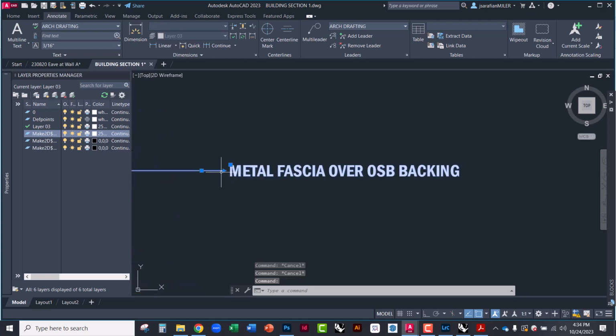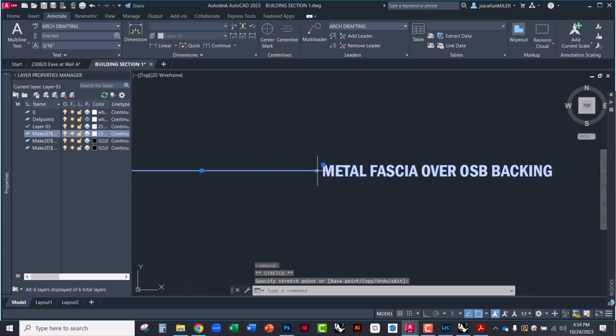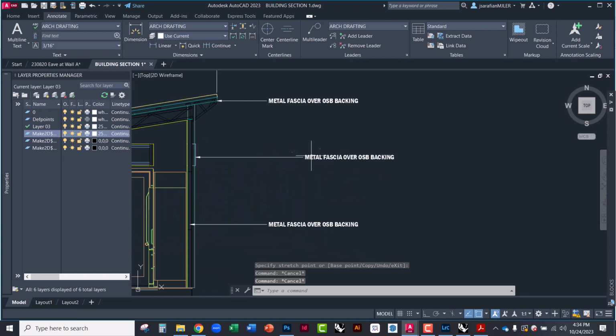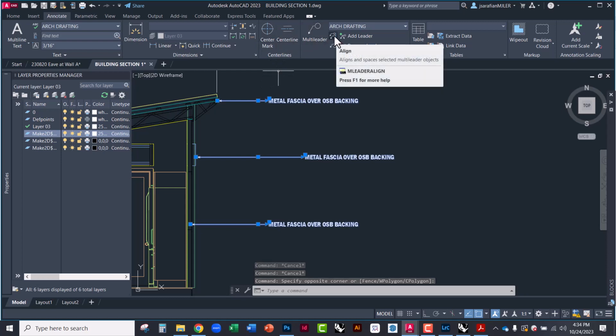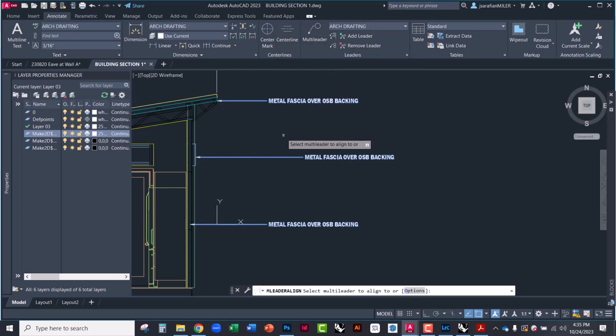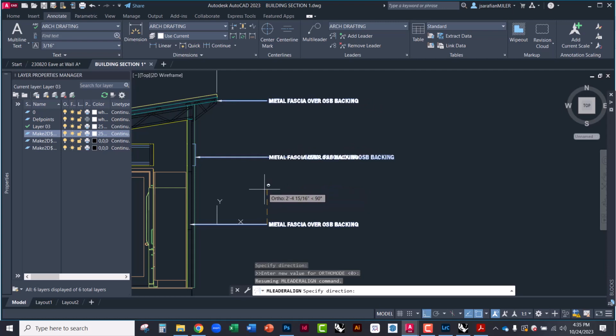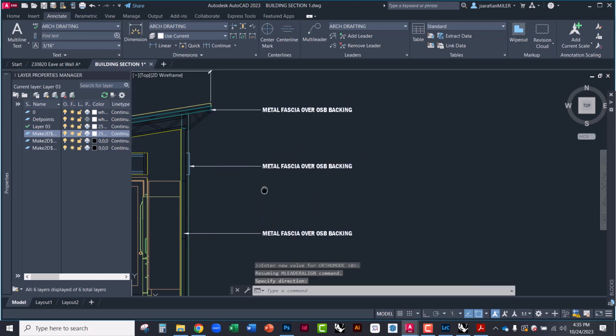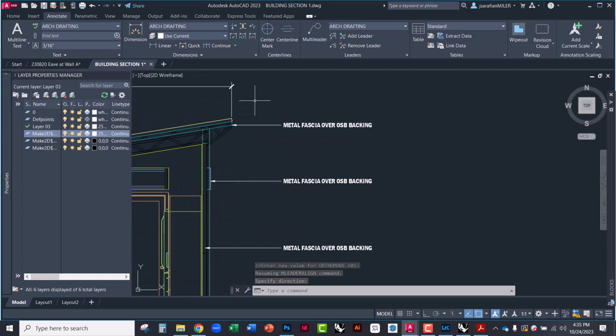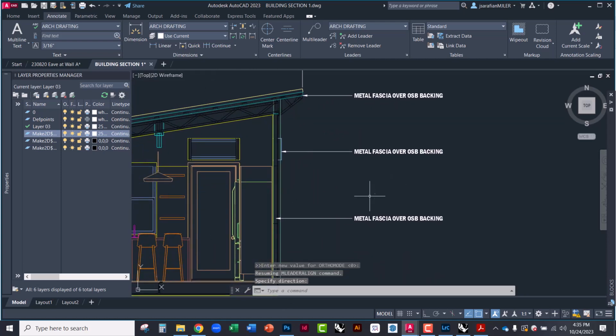And let's say when I created these that maybe this was out here. There's a way to align these in AutoCAD. You can select them, and you'll see this command here. This is align, and you can select the one that you want it to align to. Right, I want that to be my guiding annotation. Then I hold shift, and it keeps it vertical. So that's a great way to align many different annotations at once.